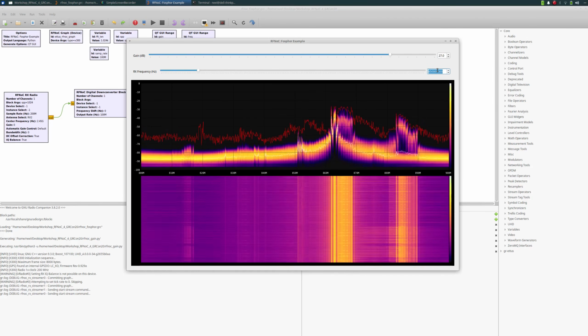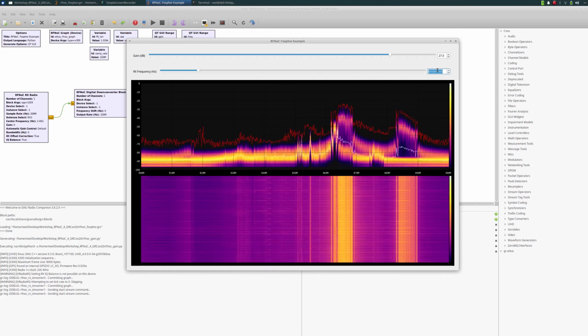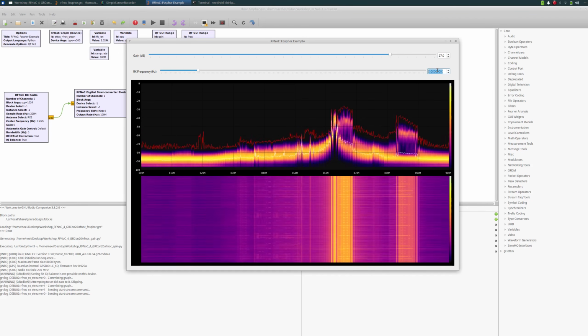(850 MHz) is LTE band 5, where from 824 to 849 MHz you have the uplink, and from 869 to 894 MHz you have the downlink. T-Mobile uses band 5. We can see some downlink signals from the nearby base stations called E-Node Bs. It looks like there's one 5 MHz downlink carrier at 883 MHz, and there is some intermittent and ephemeral activity on the uplink between 837 and 842 MHz.